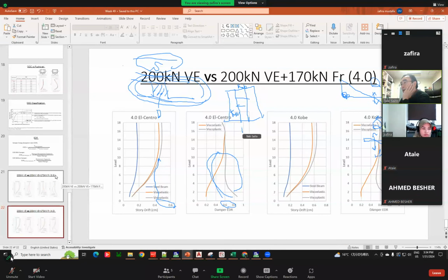And for the degree of coupling, is there any formula in case of elastic? The equation is the same: the total shear times L divided by the total overturning moment. Yeah. But for this KB, you can use an equivalent stiffness.